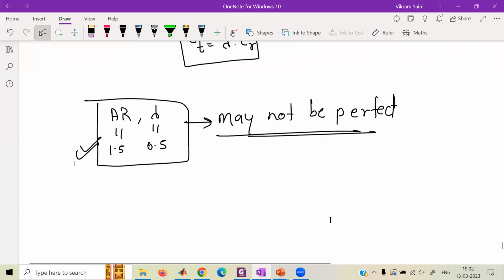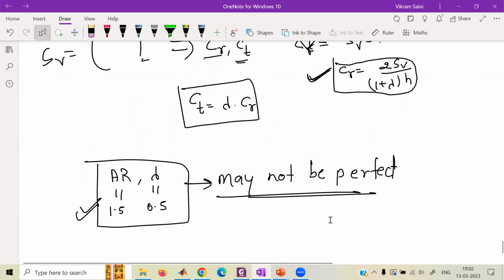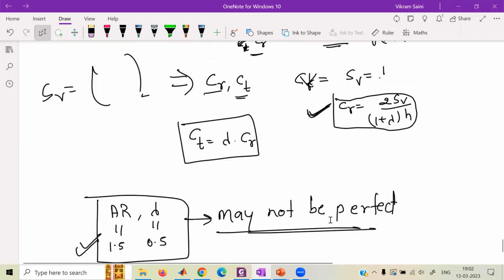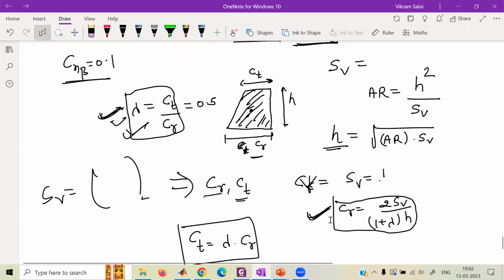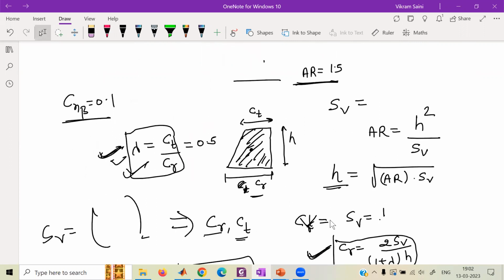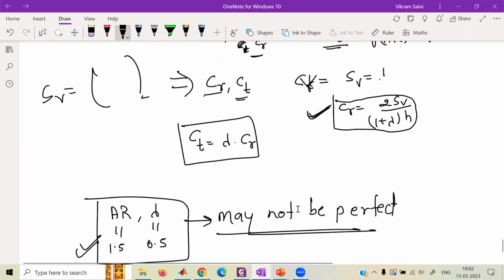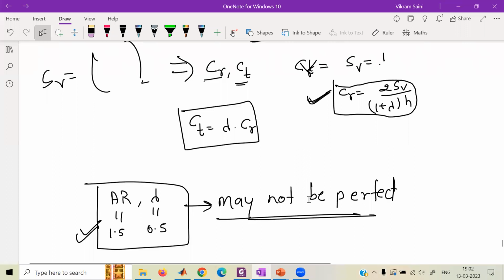Let's say these numbers worked for someone, but they may not work for you for the kind of airplane you're making. Then what is the next step to find out perfect numbers for AR and lambda? Because once you know aspect ratio and lambda, you have all other numbers. You can establish that stability requirement guaranteed. But you had to make two assumptions on AR and lambda. They are not given to you. So what should be the logical next step in optimizing aspect ratio and lambda?